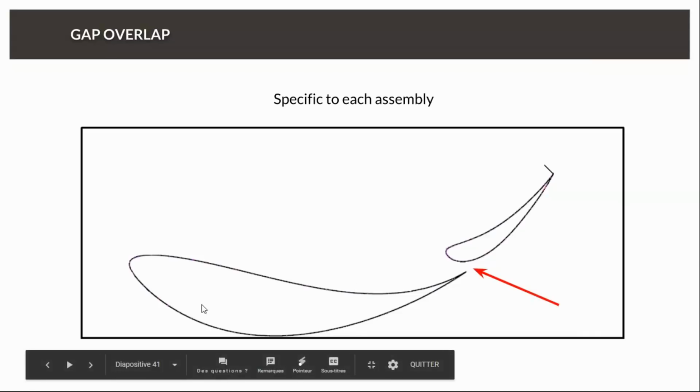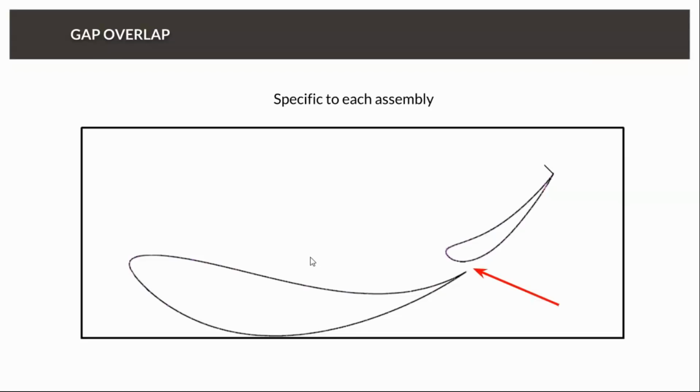But if we want more downforce and we arrive at the limit of the curvature of the main plane, and the flow starts to separate because the recompression is too big, then we will introduce a slot gap, and the complete curvature of the wing stays the one made through the two elements, but the additional energy from the top air will help the flow to stay attached, and we will hence be able to go to a higher level of downforce by increasing curvature.